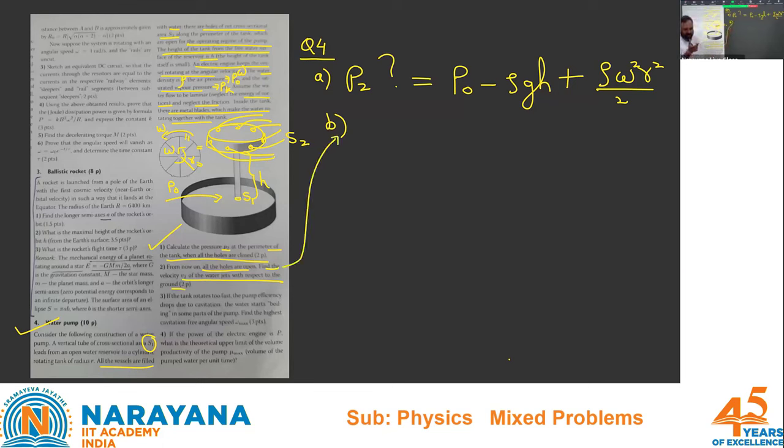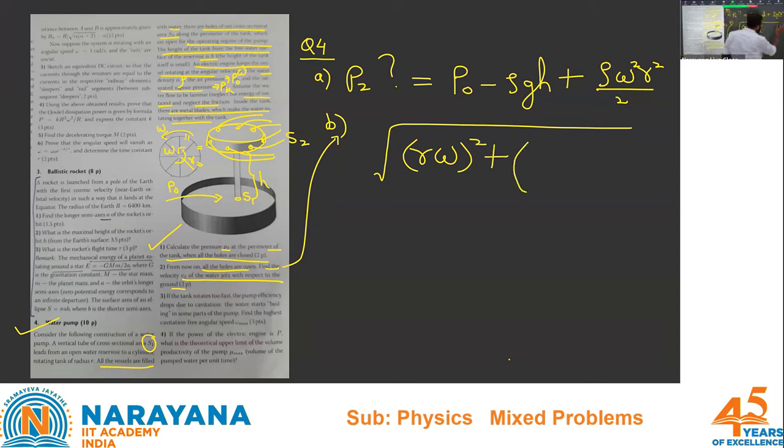Write carefully, because the pressure that you have got there, and outside pressure is P naught. So that term half rho v square will give you some velocity. The answer to this question should be root of, because they will have two velocities, no? The upper one is rotating with omega. So all the liquid which is coming out will have a tangential velocity, which is r omega. So r omega whole square plus the relative velocity square term. And if you write this pressure and P naught and write it as half rho v square, so that seems to be what?